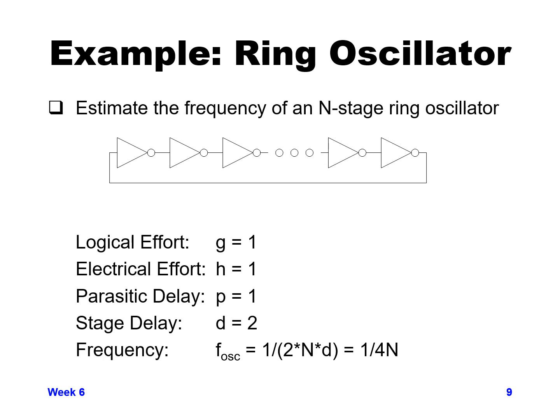And like I said, in order to oscillate, go from 0 to 1 and back 1 to 0, you need to do that 2N times. So we have 2N times d as the amount of delay to get through the ring twice, and then your frequency would be 1 over that delay. So that comes to a frequency of 1 over 4N normalized delays.